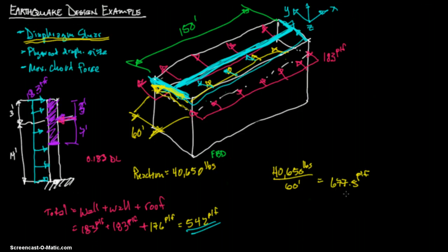Then you take this number and you go in. This is our minimum we need. This is what it's seeing, so therefore we need a capacity that's greater than this. So let's go to that table I just mentioned on page 98 in the study guide. And once again, this is the UBC. It's reproduced from the UBC table